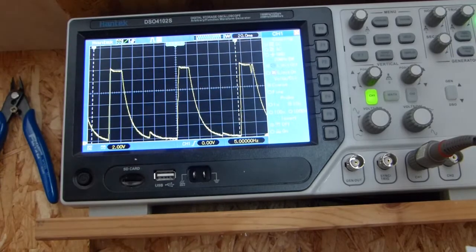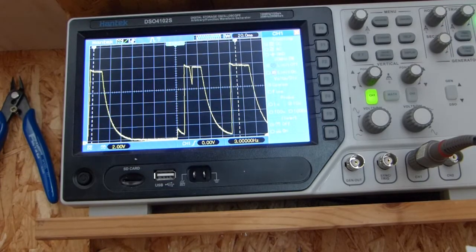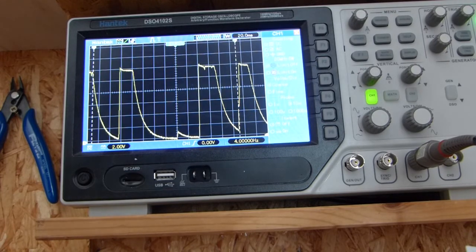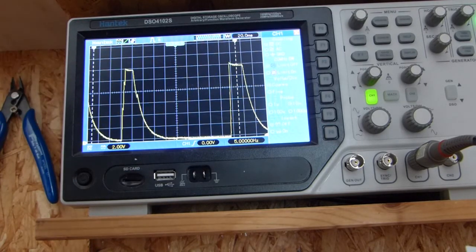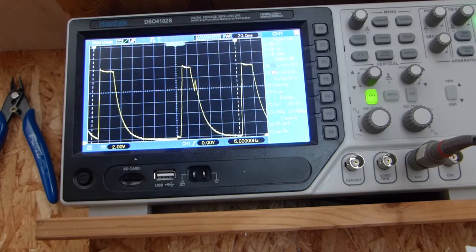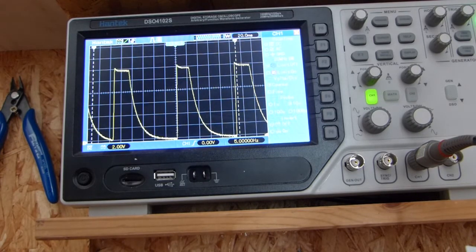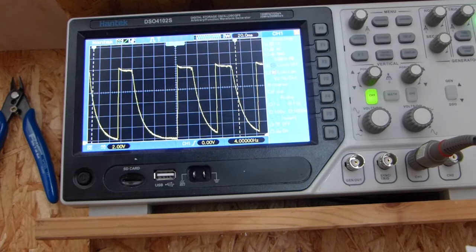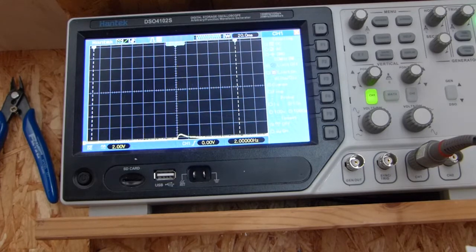Now this diagram shows the signal behind the impulse former. This is a stage that makes rather sharp impulses from the slow signal curvature you just saw. And by turning a potentiometer, I can adjust this a little bit. So now it's almost gone, and now it comes slowly up. This would be one setting that was very interesting, where the signals are going up and down, and when I turn the potentiometer more to the right, the signals become stronger.